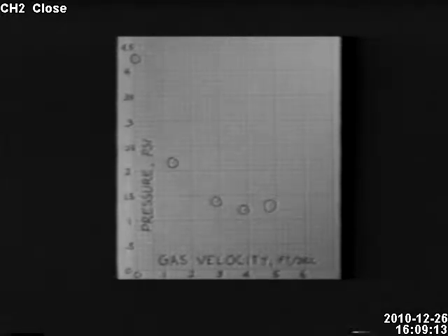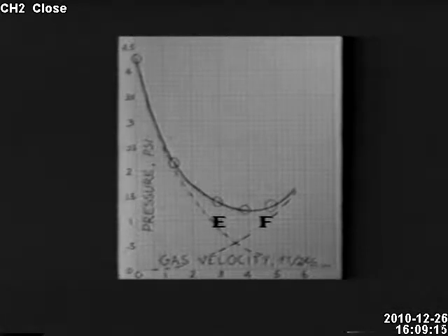Pressure drop in upflow is thus the sum of elevation and frictional effects. Increasing gas flow causes the elevation head to fall and the friction loss to increase. Total pressure drop then goes through a minimum, as our measurements show. If too large a pipe is used, system flow capacity may be impaired. Operation in the low velocity range also tends to be unstable.